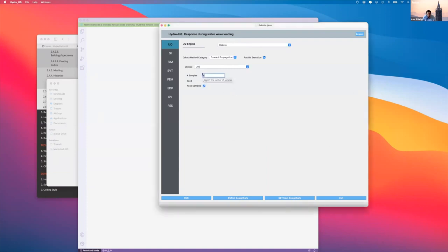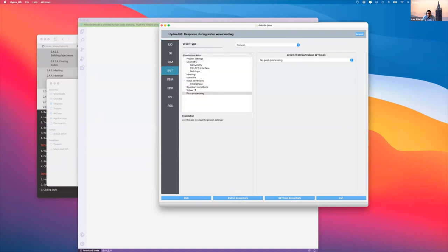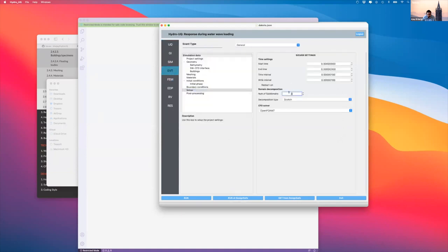But you also need to be careful about the domain decomposition you're giving here. As long as this is less than or equal to the number of processors you're using, that should be okay. For example, let's say you say I want 20 processors, but I divide into 32 domains. It only finds 20 processors to send your job to, but then 12 or more of the domains cannot be sent anywhere, right? So this can be a problem. You need to be careful of how many domains you're dividing. In the next version, I will make sure that we connect these things, and it indicates that you're using fewer processors, so that you don't have to worry about this. Are there any questions?